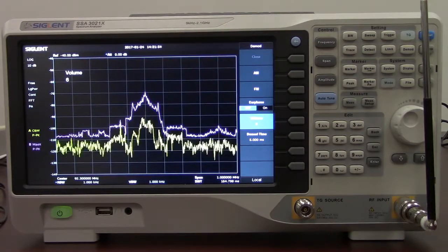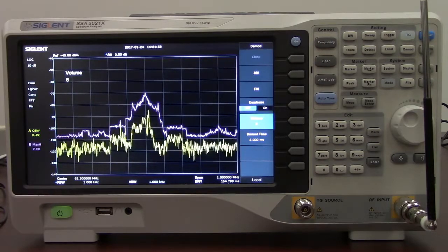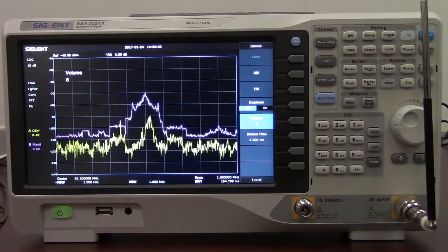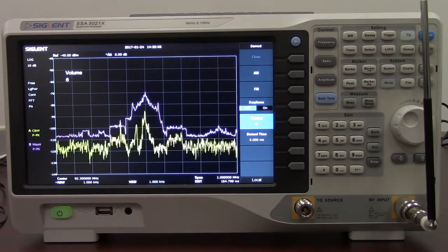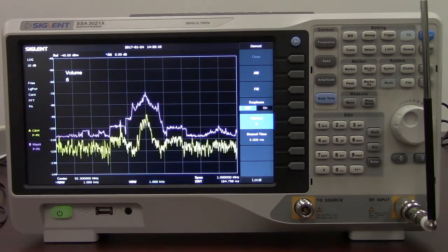transmission. So again, a spectrum analyzer is very helpful for being able to monitor transmissions, being able to tell whether you're stepping outside of your particular given band, or if someone else is stepping outside of their band and happens to be infiltrating the bands next to them. So it can be a very helpful instrument for that particular measurement type.